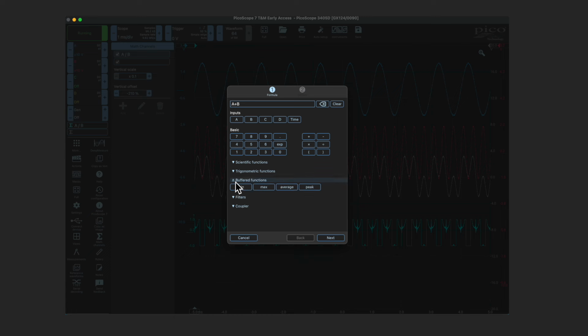There's a category that we call buffered functions. So basically they can provide you, for example, the average of any capture that was already done since the device was powered on. So the whole capture memory of the device is basically in there. We got filters, and we got quite a lot of filters. For example, also a band stop filter here. Let's just select that one.